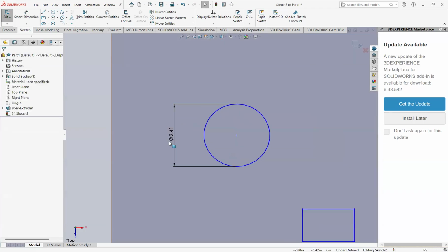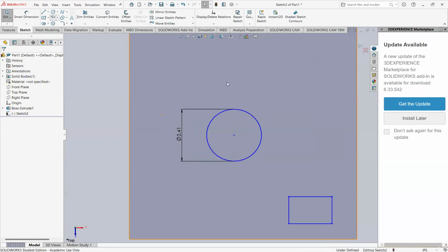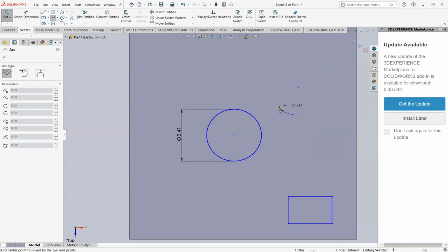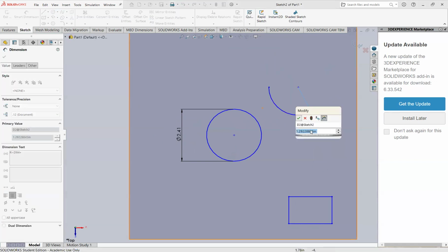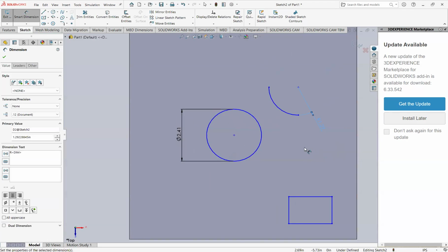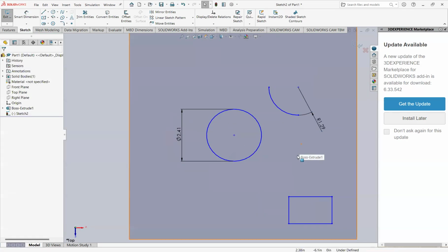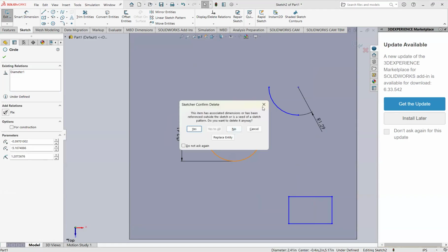You see this circle line represents the diameter. If I grab, for example, a center point arc, just to show, and I want to smart dimension it, it'll have an R, and the R represents the radius. That's very important to know, because later on, in the drawings from the exam, they'll have R's in these little circles and lines. It's very important to know the difference, because if you mix these up, the math can be extremely off for your parts or densities. Awesome. We'll delete this.